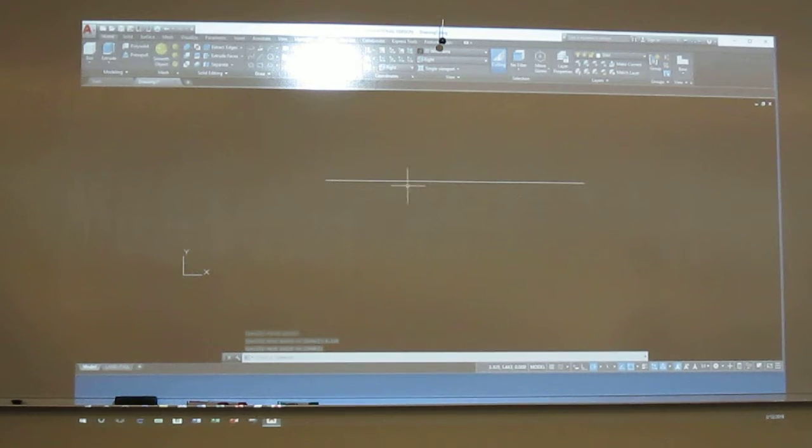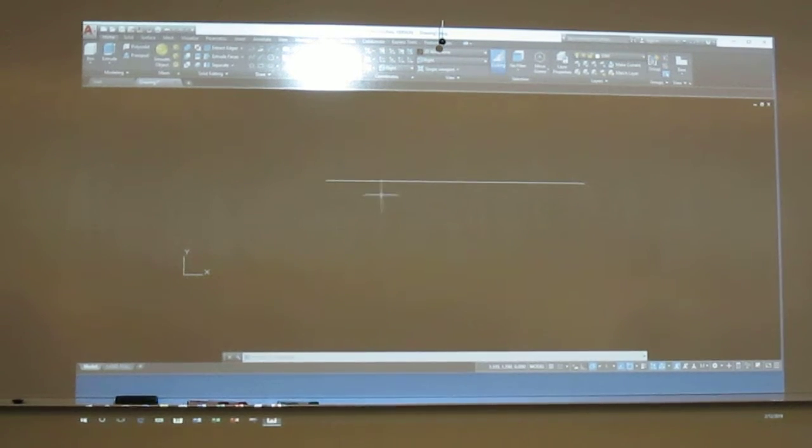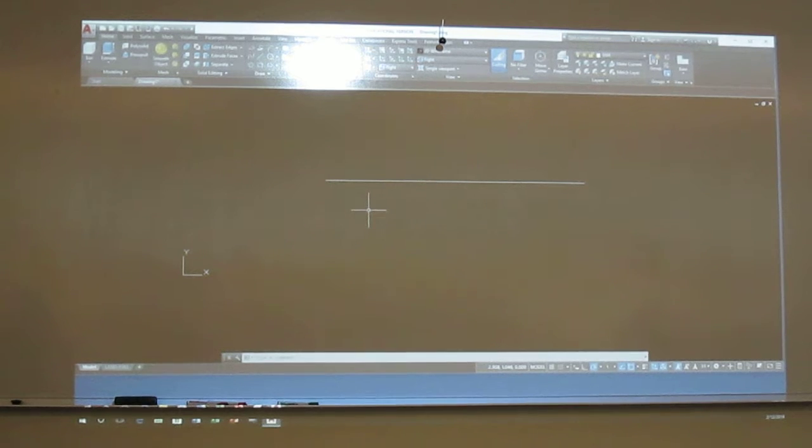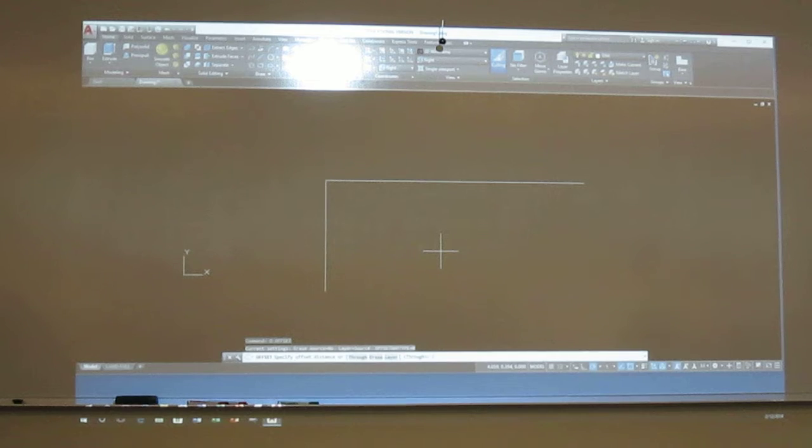Now for the drawing process, I am going to need all these different offsets that go on. So I'm going to go ahead and create myself some snap points. I'm just going to take a line, shoot it down a ways, and I'm going to start doing offsets on this line for everywhere my shape changes. So I'll do an offset. The first one is